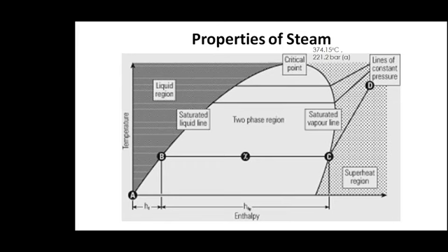So nowadays, the trend is to go in for pressures in the power station which are more than the critical point, that is more than 220 bar. So you operate at 240 bar steam, latent heat is zero. And the turbine would like it because there's no chance of condensation. Then you also get a higher efficiency.